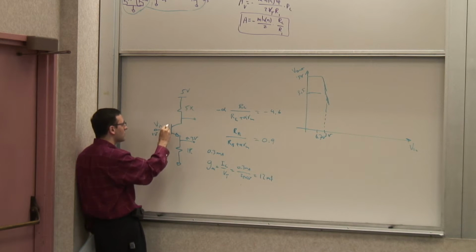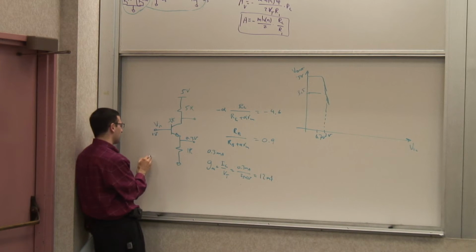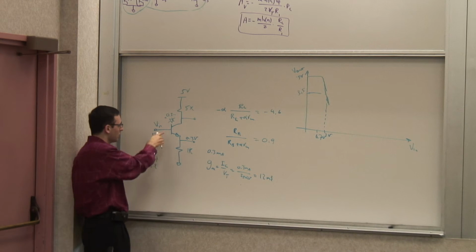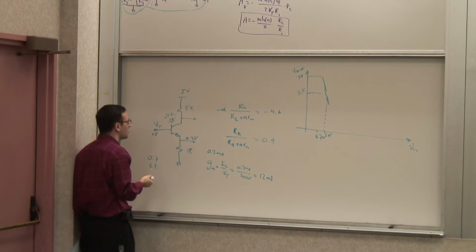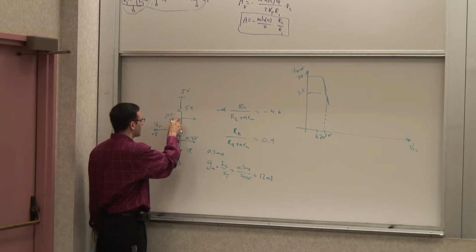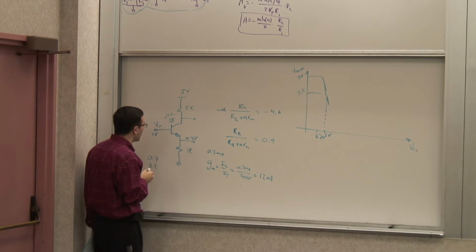So at some point, I have to worry about this diode here getting forward biased. The way I've defined it, if the VBE on is 0.7 and the VCE sat is 0.2, it means it takes 0.5 volts for this to turn on. 0.7 minus 0.2. That means basically when the base voltage becomes 0.5 volts greater than the collector voltage. So how do I determine that?